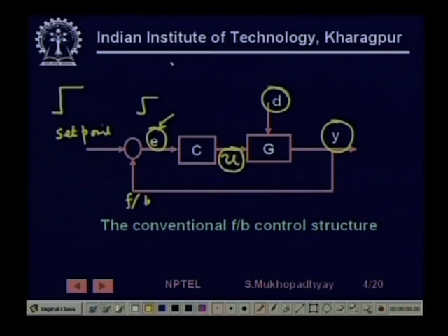For example, suppose we are trying to maintain the angular position of a motor, which could be related to other positions by gearing, etc. If you see the structure, there is an electromagnetic torque which is the control input, there is a load torque which is the disturbance. This creates an acceleration. It creates actually theta double dot.